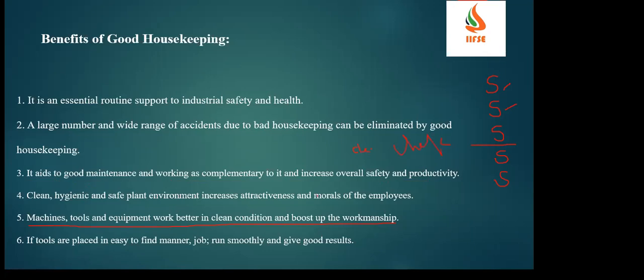Cleaning for checking means that during cleaning of a machine, we have to check for any leaks, any abnormal noise, any abnormal vibrations, whether all the controls are kept in place or not, and when the last TPM was performed. We have to check for any loose cables or damaged insulation, etc. And we have to check that all the mechanical guards are properly in place and working properly, and that all the safety controls are working in proper order.